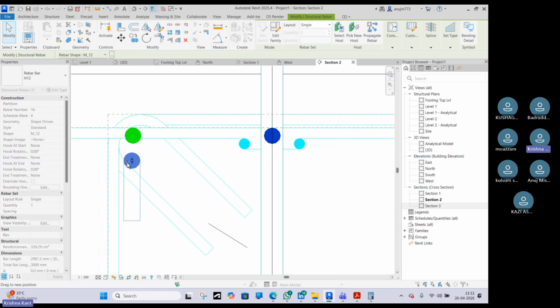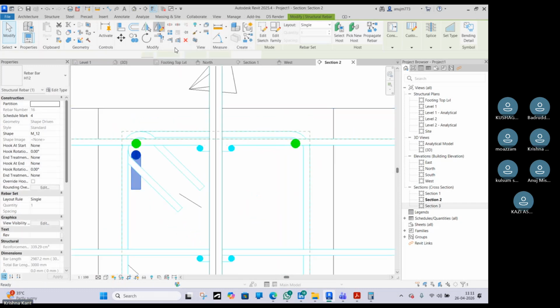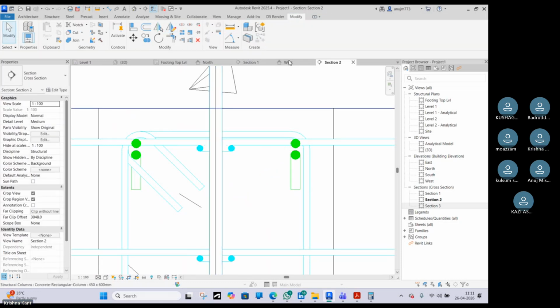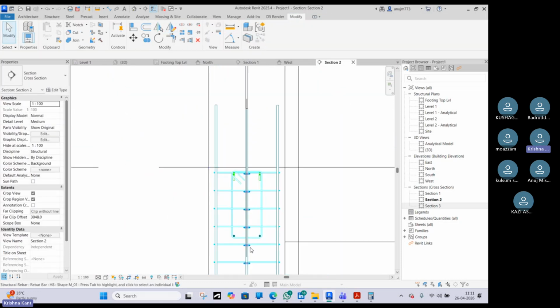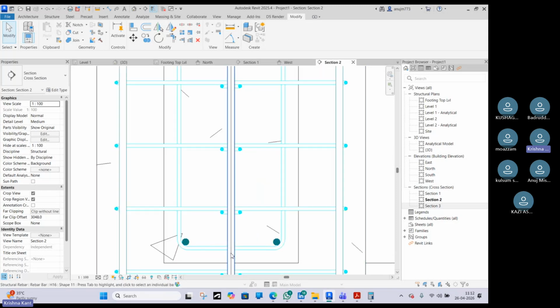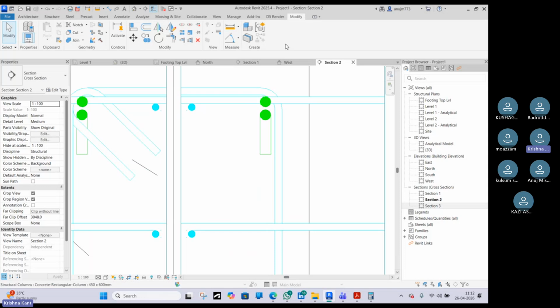So basically, we have to provide it somewhat here and mirror it. Okay, bottom extra we will not provide in the side portion. Sometimes when there is more rebar we have to provide, then only, but most probably we will provide it in the center. Suppose two bottom extra, so two bottom center we have to provide. Okay, but top extra generally we will provide on the corner.